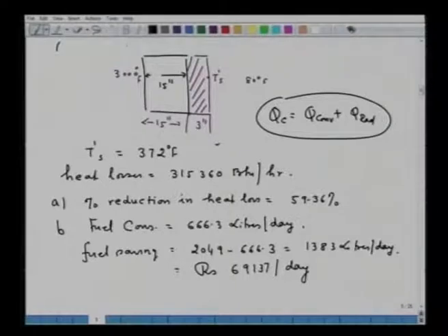Now, the last portion we have to calculate the thickness of the silica brick exposed to 2800 degree Fahrenheit is similar way. So, you have the losses 315,360, that will be equal to 400 into 200 upon x dash. I am omitting the steps, you can write down. So, the thickness of the layer which is exposed to the 2800 degree Fahrenheit is equal to 3.04 inch.